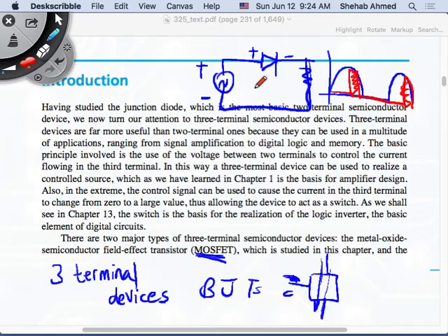I cannot do it with the diode. You cannot do it with the diode, right? Because the diode is just controlled by the external circuitry. As soon as I have this voltage applied in my external circuitry, which is this one here, I'm going to get something fixed, right? So it's not very controllable, and that's why, from a power electronics perspective, it's called an uncontrolled device.